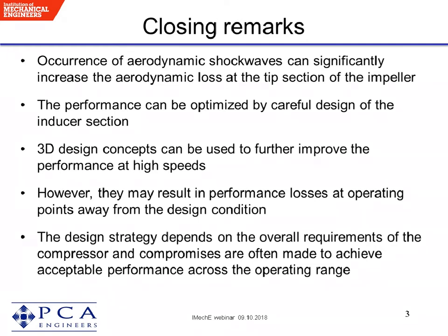Secondly, the increase in the ambient temperature does increase the speed of sound. And because it increases the speed of sound, it reduces the tip speed Mach number. And reducing the tip speed Mach number effectively reduces the pressure ratio, because the pressure ratio is a function of the tip speed Mach number. So that's the main effect of an ambient temperature increase.